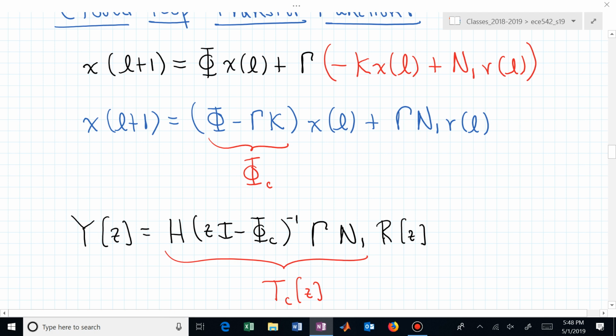As we increase zeta, we're approaching really the real line. When zeta is equal to 1, we're between 0 and 1 on the real axis, and we collapse that heart down to a flat line, so now you've flatlined, which is not really how you interpret zeta equal to 1, because zeta equal to 1 is good, probably.